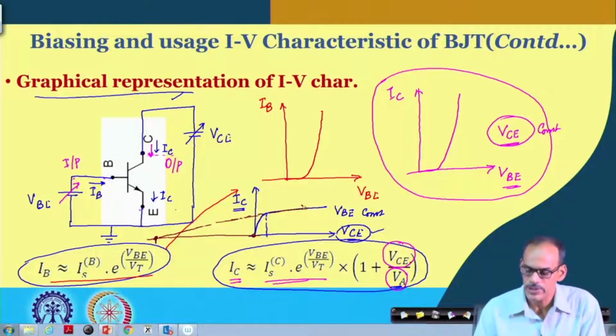the graphical interpretation of IV characteristic, they do have other meaning also. Particularly, presently whatever characteristic we have plotted, we have changed this VCE and VBE to quite a large extent, pushing the device into the heavily saturated portion. Namely, we are seeing the highly nonlinear effect from here to here.